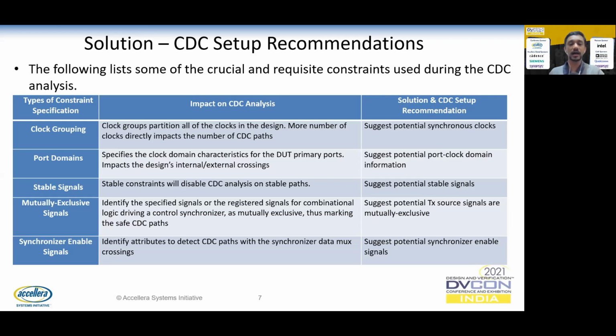Also, we have shown as a solution, utilizing supervised data mining techniques, what CDC setup recommendations can be provided to help the users resolve the unsynchronized crossings. In the upcoming slides, the results section contains the effect of these suggestions on the CDC analysis time and effort.